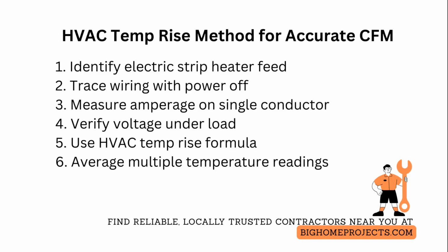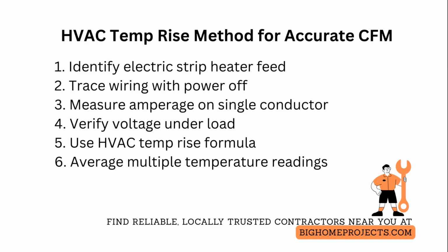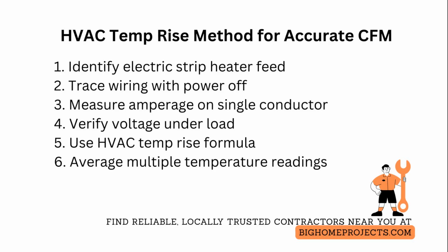That wire carries only the heater current, not the blower motor, so clamp around it to measure amperage. Confirm by tracing the wiring diagram and using a continuity tester with power off so you do not accidentally clamp a multi-circuit bundle. Next, calculate heater watts precisely by multiplying the measured heater amperage by the known heater voltage, and